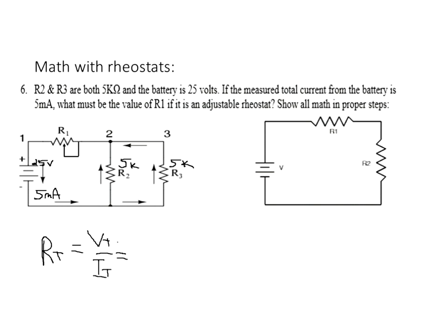Do the math. 25 volts divided by 5 milliamps to see what the total resistance of this circuit should be. 25 volts divided by 5 milliamps. I got 5 kiloohms. Okay. Now, you know the total resistance should be 5 kiloohms. That's what the total resistance has to be of this whole big circuit. This whole circuit with all of these put together is 5K. So to generate that current, I need 5K and 25 volts.